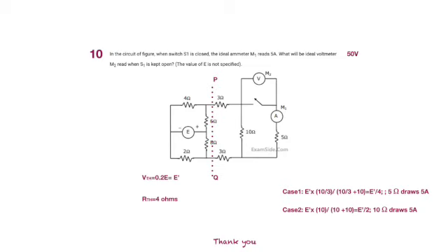So we see that whatever be the value of E, the voltage across PQ as a Thevenin's source is equal to the division of voltage of E between 6 ohms and 4 ohms, as also between 8 ohms and 2 ohms, and the difference between 6 and 8. So obviously VTH is equal to 0.2, that is 6 by 10 and 8 by 10, the difference between them is 2 by 10 or 0.2 times E dash. So that's point number 1.